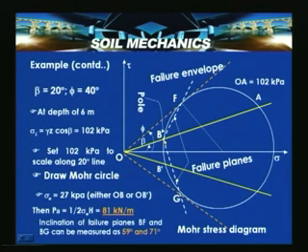So, this is point B. From the point where the pole is, if you draw a line to the failure envelope and it cuts at F, then the circle passes through F, A and B. If you draw a Mohr circle, you can construct it by satisfying these conditions.